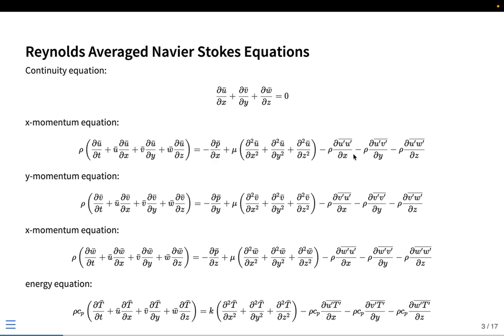In general, when we are doing the averaging in normal Reynolds averaged Navier-Stokes equations, averaging is done in terms of time. So the effect of unsteady terms would actually be gone when we have done that. The main difference between these equations and the ones that we have seen before is the appearance of two things. One is the bar on the top of each of these quantities, which represents that these quantities are the average values. Average values in the sense that they have been averaged over time, and there is a prime quantity which are